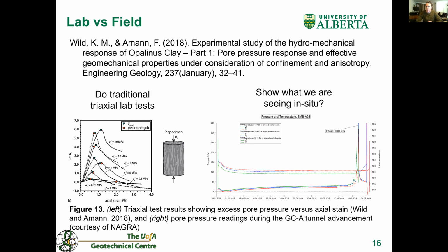The purpose of this task is relatively self-explanatory. We hope to observe a direct link between the pore pressure response in the field when compared to the lab setting. The things that we hope to quantify through this process include the discrepancies between the strain to failure observed in situ versus in a lab setting. Failure has generally occurred at small strains in situ, leading to much smaller yield values than what has been predicted through traditional lab tests.